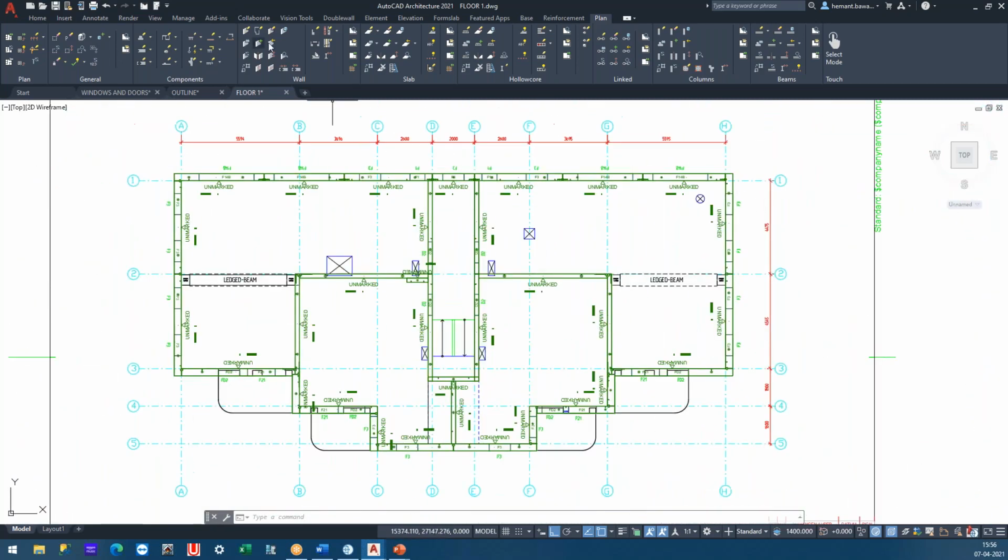So what we'll do is we'll save these walls. We'll select all of them. I will select the element type sandwich walls, and we can start with any number we like, but right now we do not have any element marked, so it will start with 1. We can specify if we would like to change that. Maybe I can do it 101, 1 for the ground level.